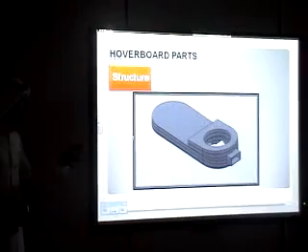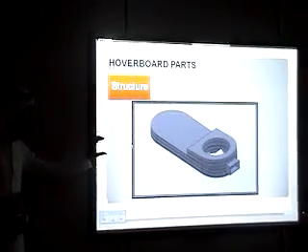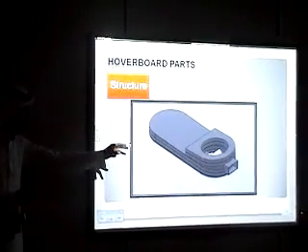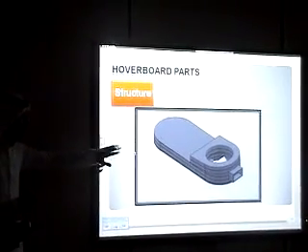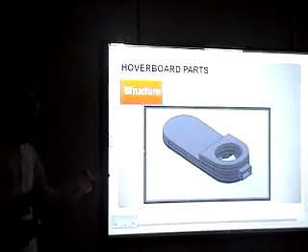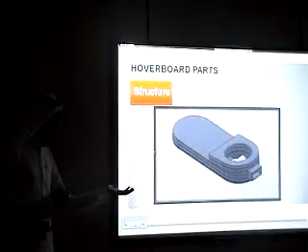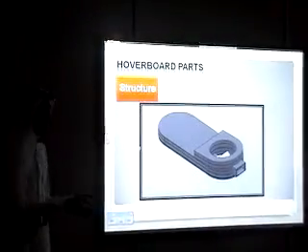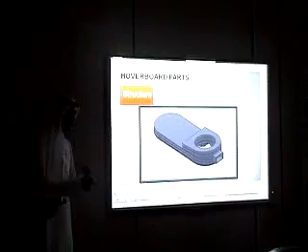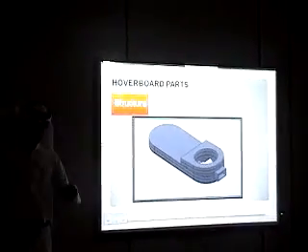The structure of our hoverboard is made of a sandwich of foam, and there are three plates of foam under the engine, and the upper plate and the lower plate are made of plywood, and we covered them with fiberglass to make them stronger. We use this skirt to keep the air under the hoverboard to increase the pressure.